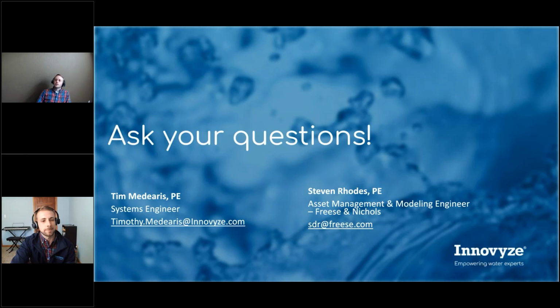Those can have a big impact on how much head is generated across the sluice gate. So looking at those and evaluating just what those values should be set at, you know, how much head is this sluice gate really generating if it's wall mounted and it's the full width or beyond of the channel. It's not going to have as much impact if it's kind of in the channel proper.